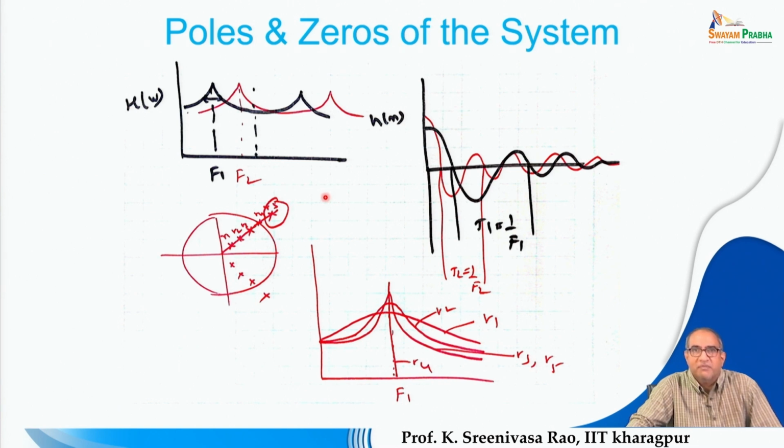or max phase system. And if some poles are inside and some of them are outside, it is known as a mixed phase system, because the poles and zeros that are within the unit circle offer the minimum phase, that means they offer the damping and try to converge the system. Whereas the poles and zeros that are outside the unit circle are responsible for growing sinusoids, so they try to pull the system towards instability. So, it is a mixed phase system, right.